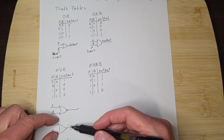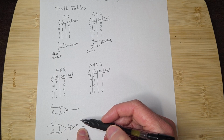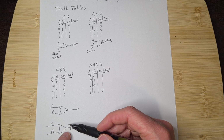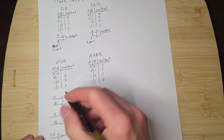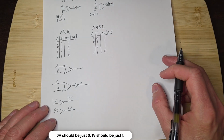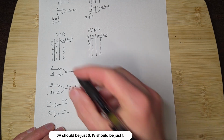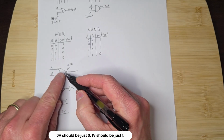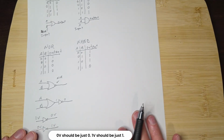If I have 2 zeros, the OR gate's going to be 0, and I'll get a 1, right? And if I had a 1 on either one of these, I'd have a 1, and it would turn it to zeros. See, it's just inverting. That's why they call it a NOR gate, because it's not OR, if that makes any sense. That's the symbol for the NOR gate. I was just trying to explain what that little bubble is. It's just an inverter. So it's an OR gate with an inverter on the end. That's the best way to explain that.